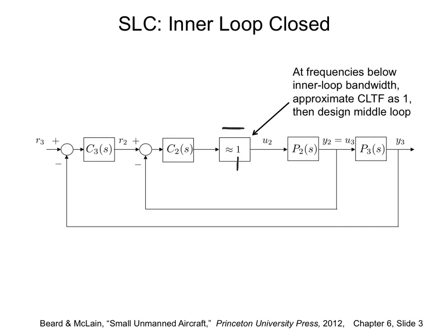So when you're obtaining the gains of the outer loop, you can consider the inner loop DC gain equal to 1 or k theta or whatever that DC gain is. That means at that frequency, it is just a steady state value, which can be equal to 1 or k DC. This is the DC gain that we can use.